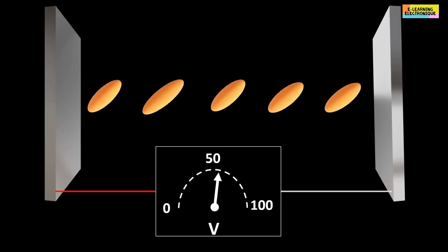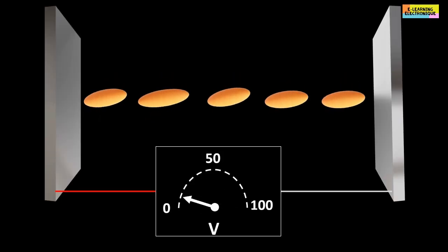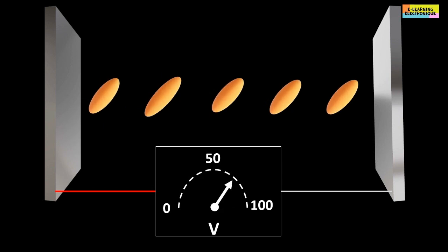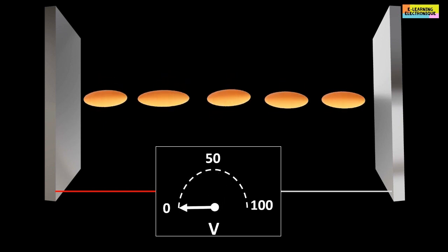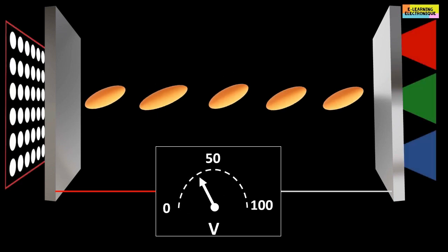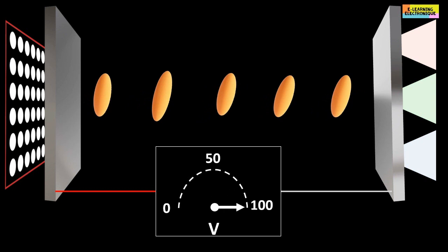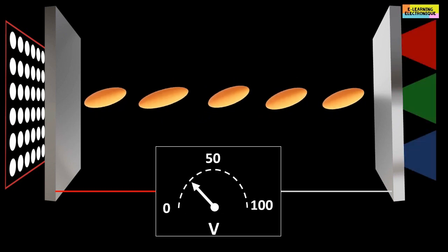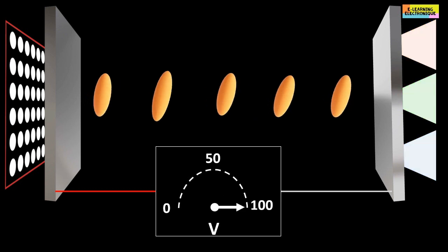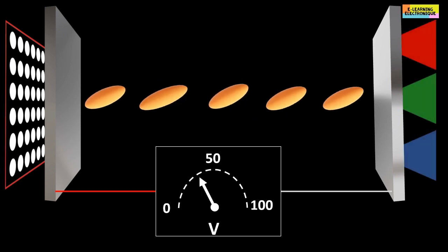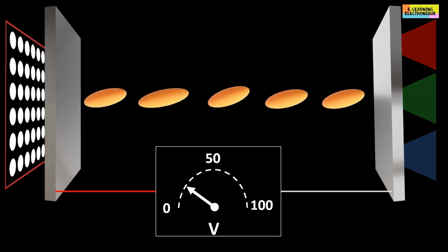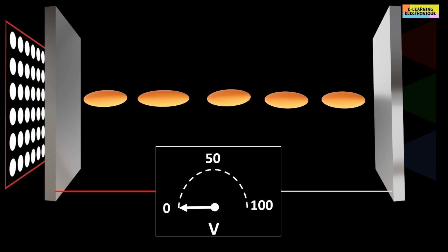The liquid crystal is used because it has optoelectric properties which allow it to modify the orientation of these crystals when it is subjected to an electric field. Depending on the electrical voltage applied to the liquid crystal armatures, the intensity of the light that passes through it will be variable. The combination of the three RGB lights with variable intensity values allows to obtain millions of different shades of colors. It is this property which is used in the LCD screens to obtain the colors.